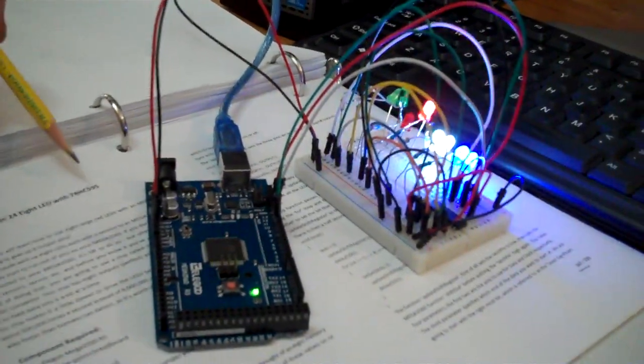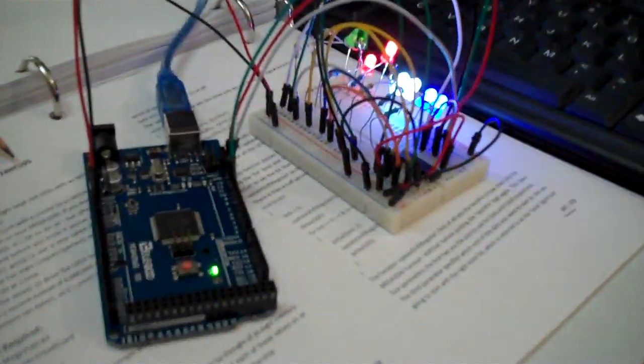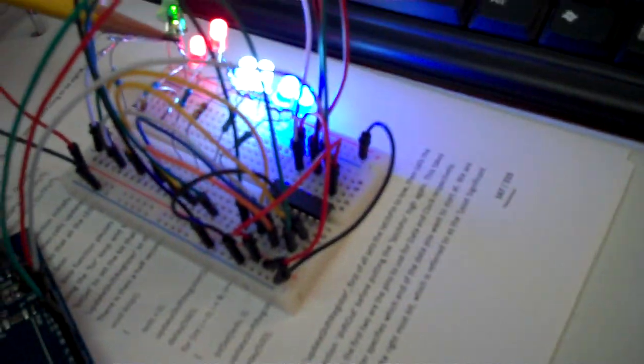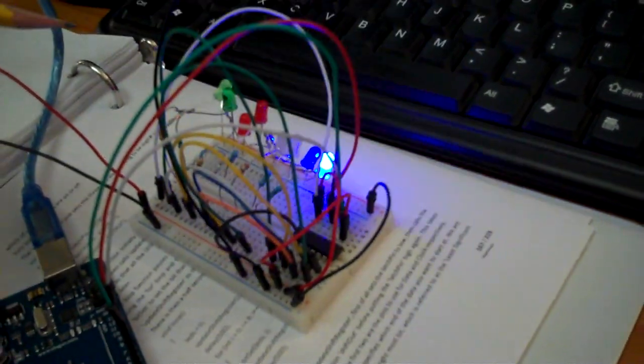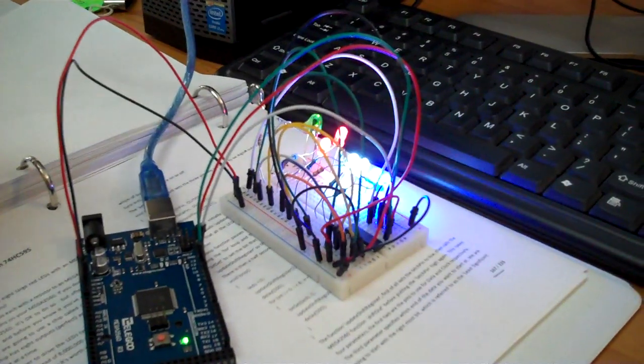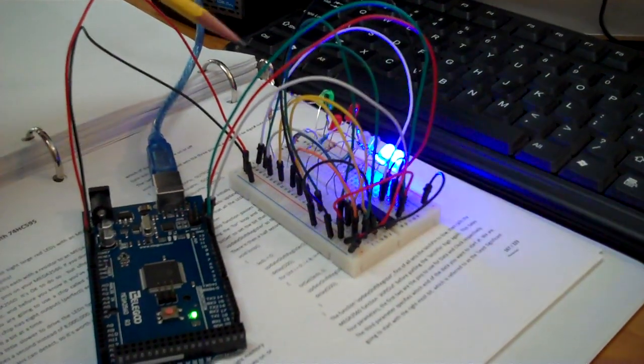The circuit that's being set up here is an 8 LED with the 74HC595 register. What that's going to do is that when it is clocked, it's going to load a logic 1 out to each one of these LEDs. And it goes low and it'll reset, and the clock will cause us to shift along to each one of these LEDs on the output of that device.